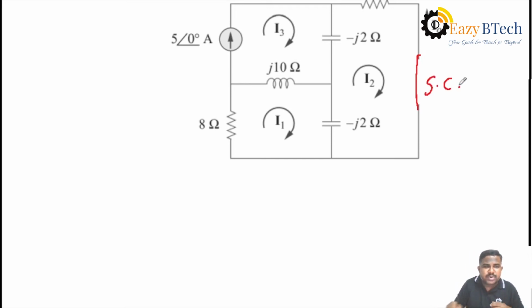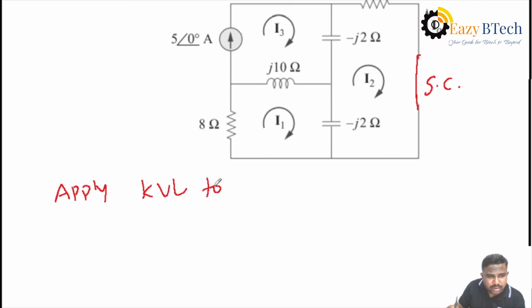Okay. Then simply understand, after deleting the voltage source, the circuit becomes three loops. I1, I2, I3. Then you can find out all the currents by applying KVL for each loop. Then apply mesh analysis, nothing but apply KVL to the first loop, that is loop 1, where I1 is passing here.